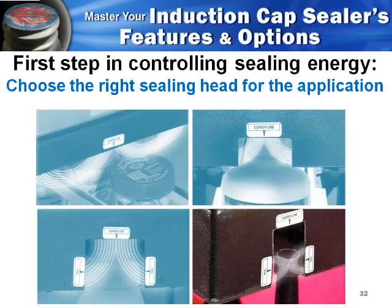The lower right picture that you see now has the fields emanating a little differently than what we've seen before. Our deep tunnel coils will emanate the field from the side to get more effective heating. You see in the picture here we've got a pretty small closure. We'll typically use a deep tunnel coil like this on a product that has a 20 millimeter closure or smaller. We'll also use these in cases like we saw in the mustard picture before, where you've got the foil a long distance from the top.